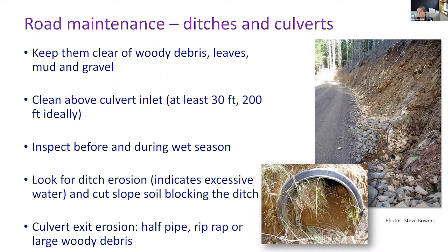Look for ditch erosion. This ditch erosion indicates that there might be too much water accumulating. So you might need to place an additional culvert further down the road, so there's not too much water accumulating.